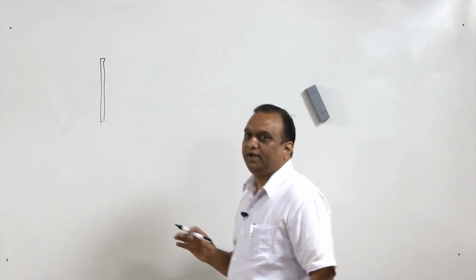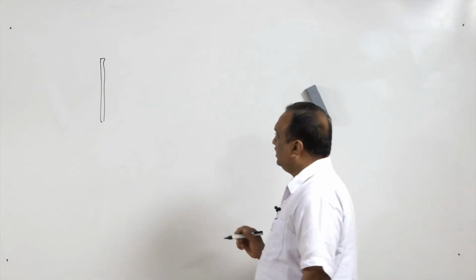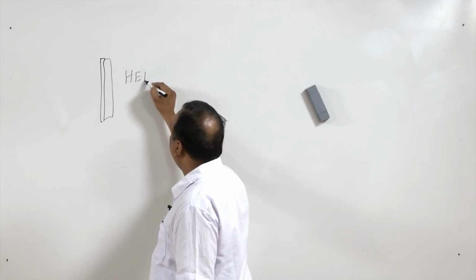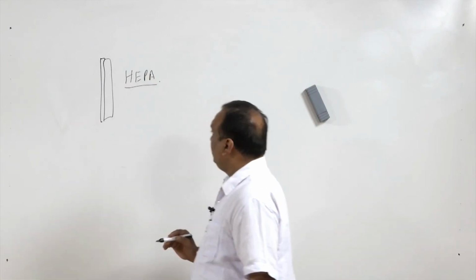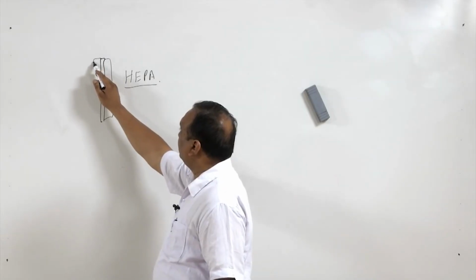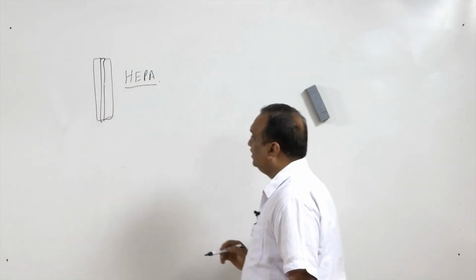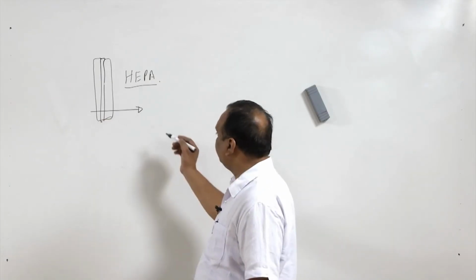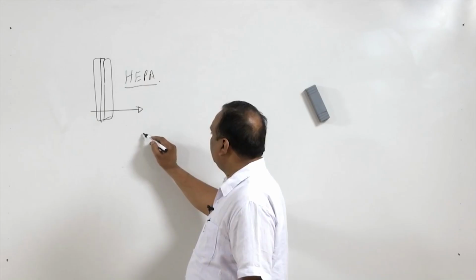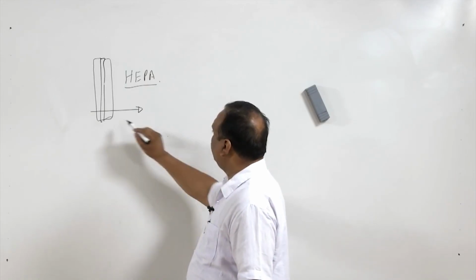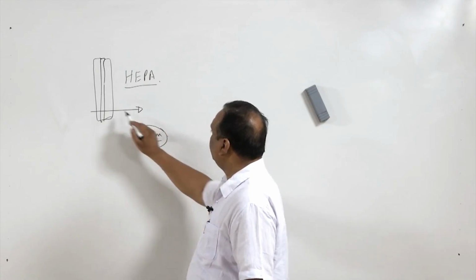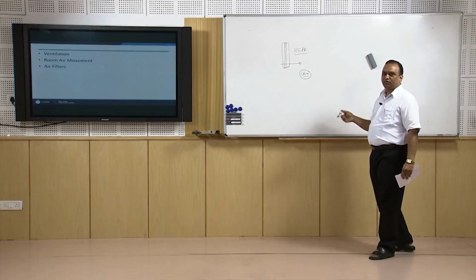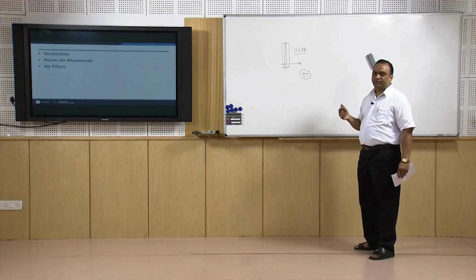Mainly infection takes place through bacteria or virus in healthcare units. So, certain filters are provided. One of the filters is HEPA, high efficiency particulate air filter. If we use 3 layers of this filter, we can even prevent the entry of bacteria in the confined space. Normally the bacteria size is approximately 1 micron, and the movement of this bacteria is prevented by HEPA filters. So, they are commonly used in the bypass surgery room or surgery which is very prone to infection.